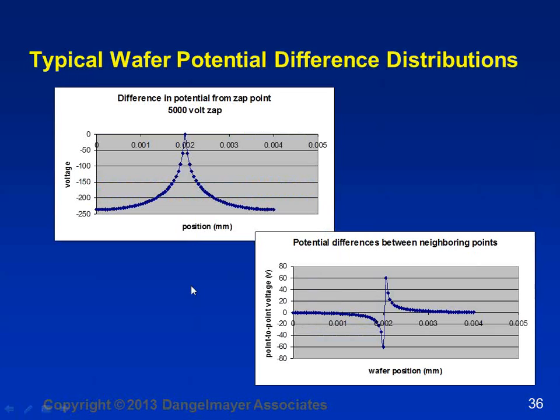The results of this work showed that on the active side, now again the stress is on the backside at 5 kV, the rear of the wafer, we were measuring, or calculating, up to 250 volt stresses on the active side of the wafer. And depending on the specific parameters of a wafer, this, of course, could change. The bottom line is that you're going to start seeing, if you haven't already, ESD failures at the wafer level.